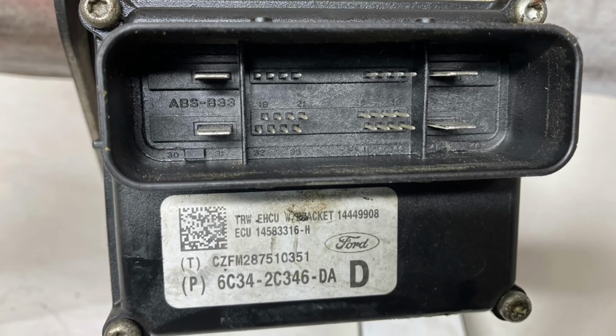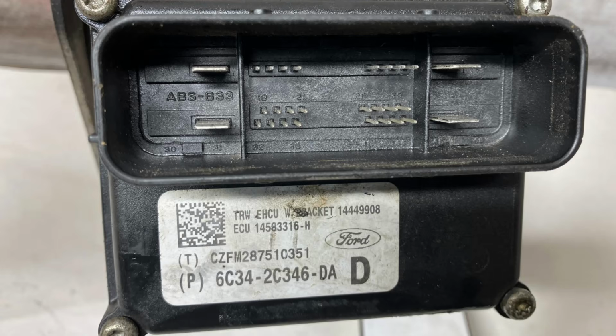Finally, the ABS module may be faulty. I wouldn't say it's a very common problem in Ford cars, but if you've tried everything and couldn't find the culprit for the U0415 code, the module will need to be checked by a good mechanic. Anyway, I hope that you will fix the issue by testing and charging the battery, replacing the faulty wheel speed sensor.